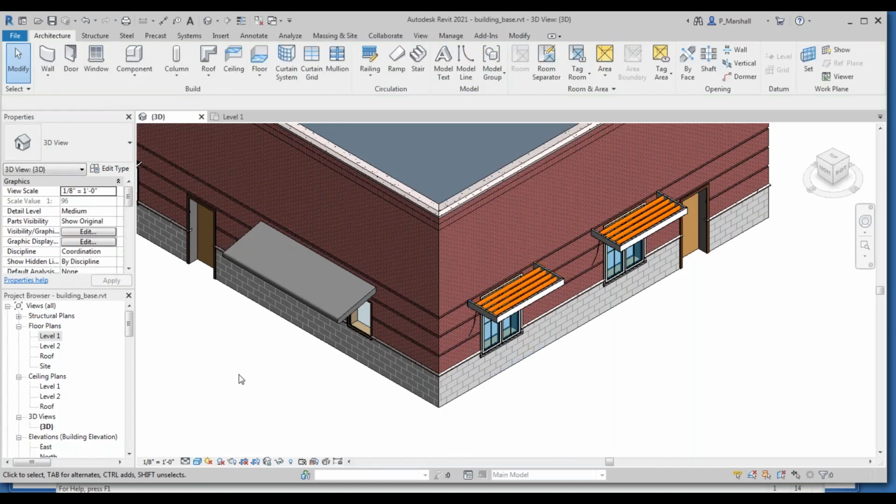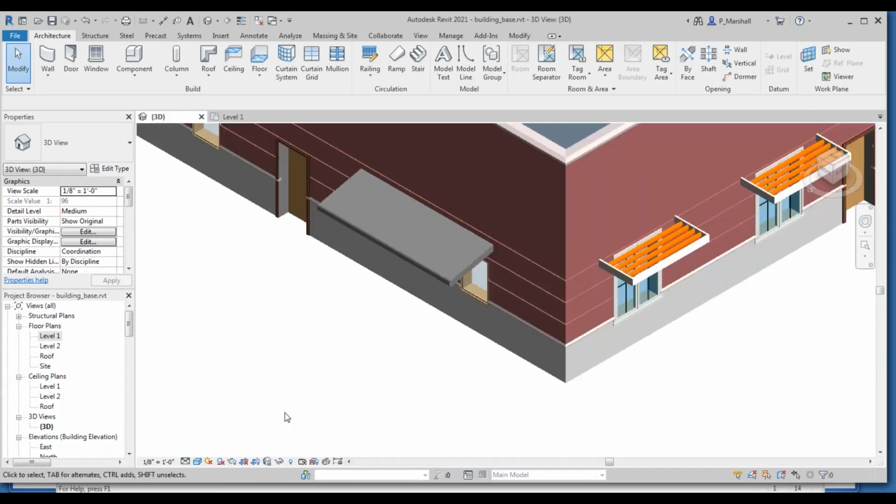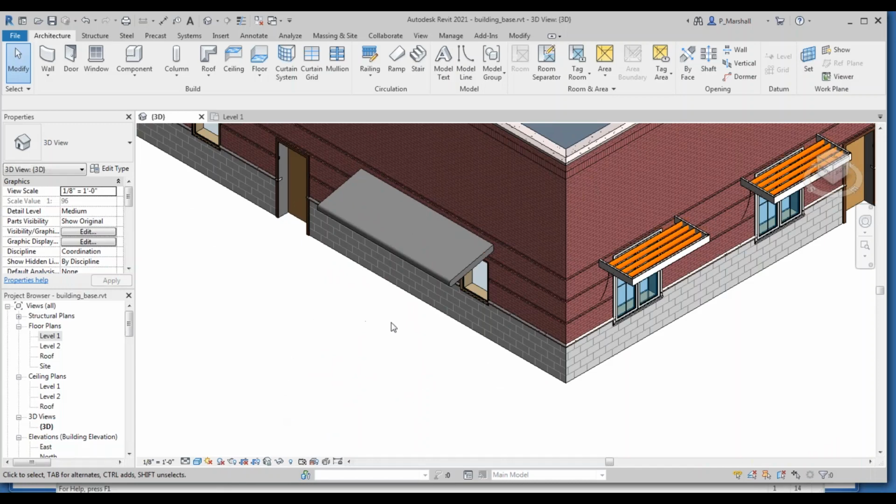All right, so that's going from the manufacturer to the architect. Now let's look at the other way around, where the architect provides the design and the manufacturer makes it. So this is a totally custom sunscreen. Using Revit, the architect for this building has already created a different kind of sunscreen, probably making it a built-in place family. This geometry can be linked into the Inventor model for further detailing it. And once you have that, then the manufacturing methods can be decided and optimized.